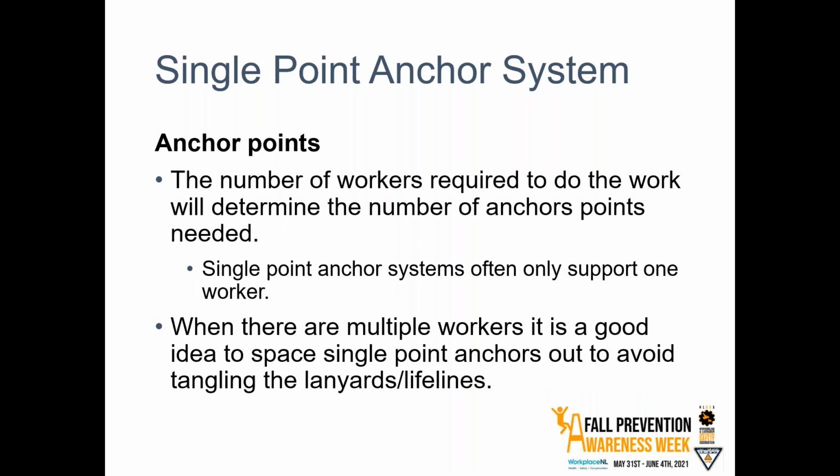Again, to highlight that usually anchor points are only for one person at a time, but that can vary. So you want to make sure that you pick a system that is going to work for the number of workers you need to do that job. Again, you don't want more than one person tying off to an anchor if it's not designed for that. When you do have a lot of workers working together, and if you are using single point anchors, you want to make sure that you space these workers out to make sure that their lifelines or lanyards don't get tangled together. And that can happen when you have a lot of people working on a site, and really does create some trip hazards and things of that nature.